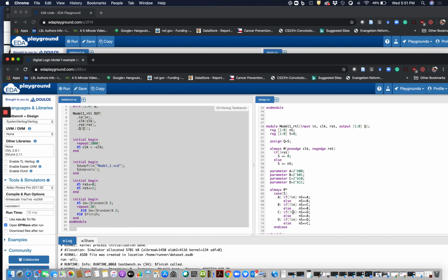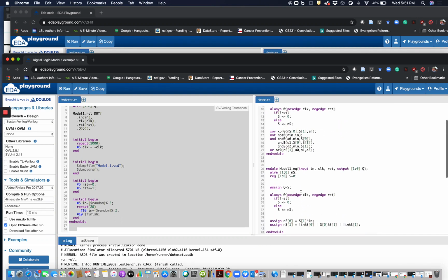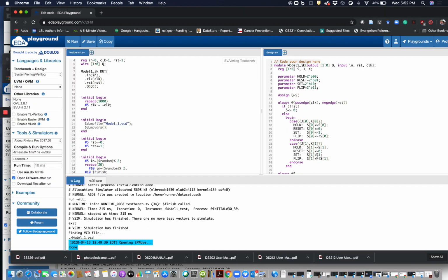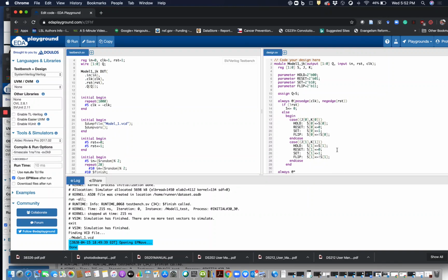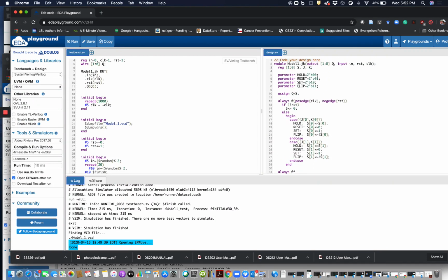Note the difference being that instead of that case statement down below, we've now got a case statement that's built into our system for the flip-flop. So the flip-flop is more complicated when we come to the new system, but that makes the regular functioning part of the system, the next state logic, much simpler. Anyway, welcome to read it. I do highly encourage using parameters when you do these because it's just a lot more readable.